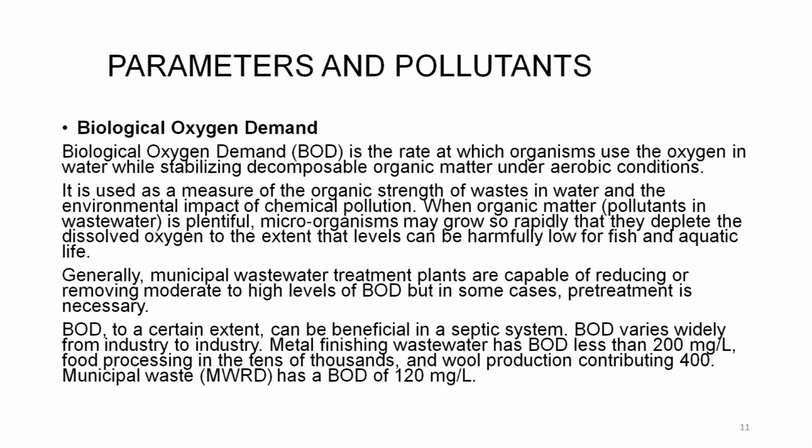So, that is the major concern, that BOD should not rise so much that the aquatic life cannot get oxygen, because all the dissolved oxygen will be consumed by the microorganism for assimilation or degradation of these organic pollutants, and it will not be available for the fishes or the other aquatic animals and plants.